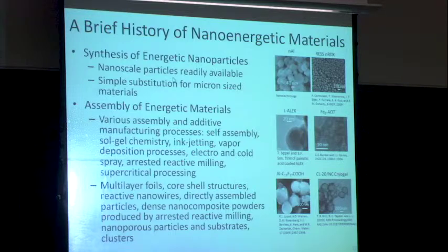As I mentioned, it was recognized early that the oxide layer is a negative feature. So the question was, can I passivate these small particles with something other than the oxide layer? Here are a couple of examples where researchers have looked at different passivation materials, in this case palmitic acid or oleic acid on aluminum particles and iron particles. The person on the right coated the iron particles with oleic acid, and here's one of their interests for doing that.